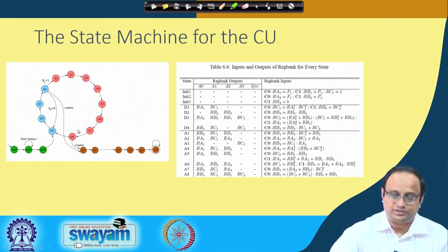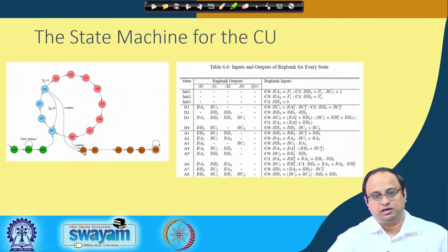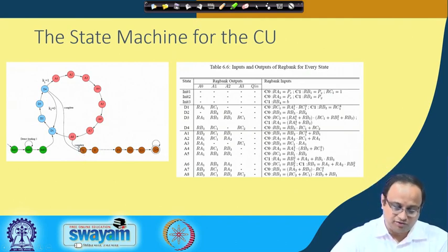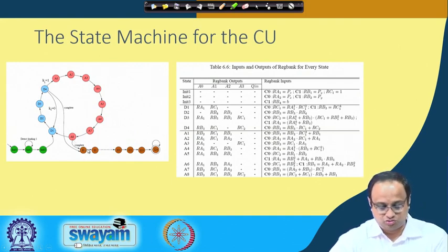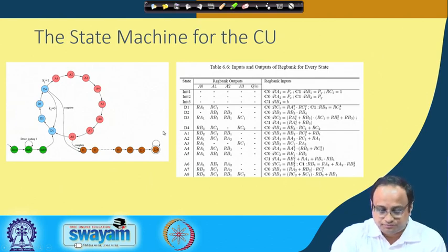But this is conditional in this architecture. Later on we will see this is not a very secure way of doing it, but at least from a performance point of view this looks fine. So you take 8 clock cycles for doing the addition. Once you have processed the entire scalar, you go for the final result, where you get the affine coordinates and the ultimate result, and for that you do an inversion. That is shown by these brown circles. For the inversion we have 24 clock cycle requirements, done by the Ito-Tsujii inversion algorithm.